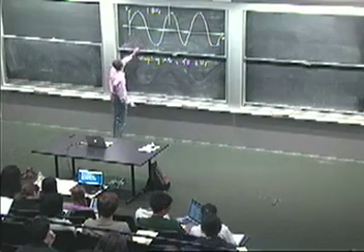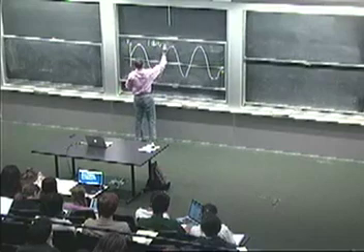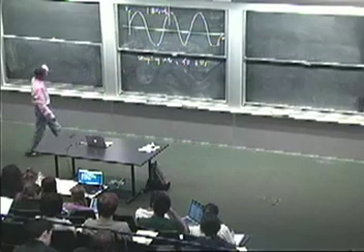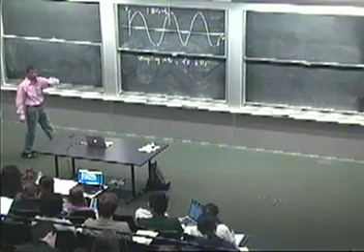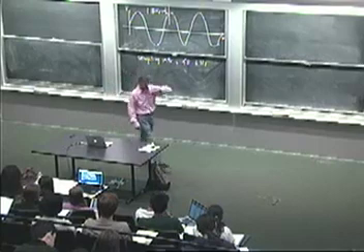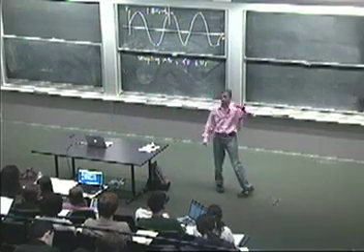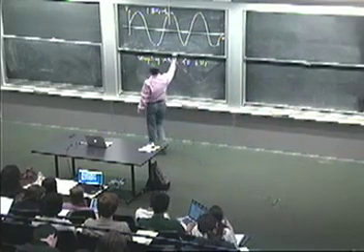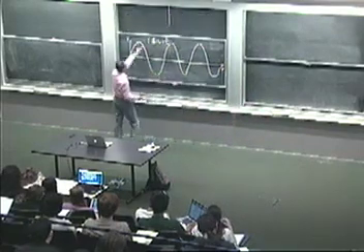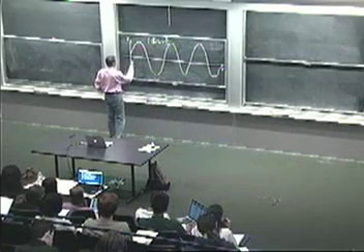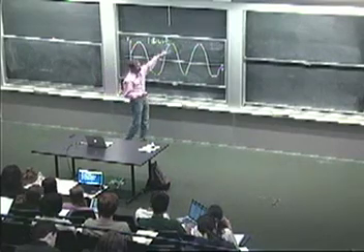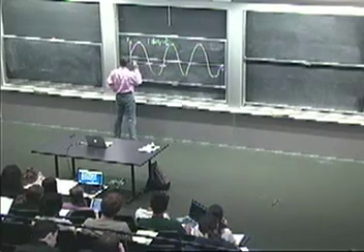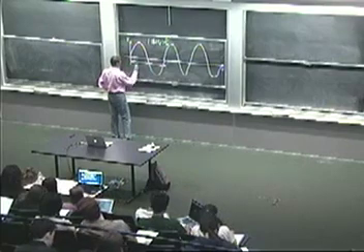So we have two things. We have the 1 kilohertz, which is the carrier waveform. We'll use the notation FC for that. And we can receive samples at 48 kilohertz. And that's how the transmitter also, when it wants to send stuff on the air, picks a sampling rate. It's going to pick 48 kilohertz. The receiver and sender need to agree on the sampling rate. What happens then is very straightforward. If you have a carrier waveform that looks like this, what 1 kilohertz means is that we do this cycle 1,000 times a second, which means that one period of the cycle is 1,000th of a second, or 1 millisecond.